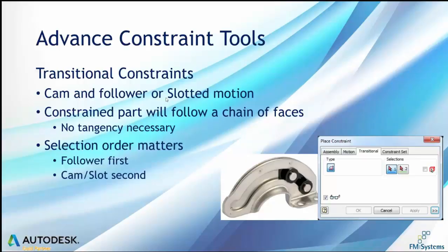Now, there is sometimes a bit of a problem with this one because it has to fit exactly. Otherwise, there's movement allowed between components. We can use this in conjunction with normal mate constraints, flush constraints, or angle constraints to make sure the objects don't rotate in weird directions. But if they don't fit in the pocket exactly, they'll sometimes jump to the outside of the component, which means we have to move it back into the center using the normal free move component before it'll stay in the center again.